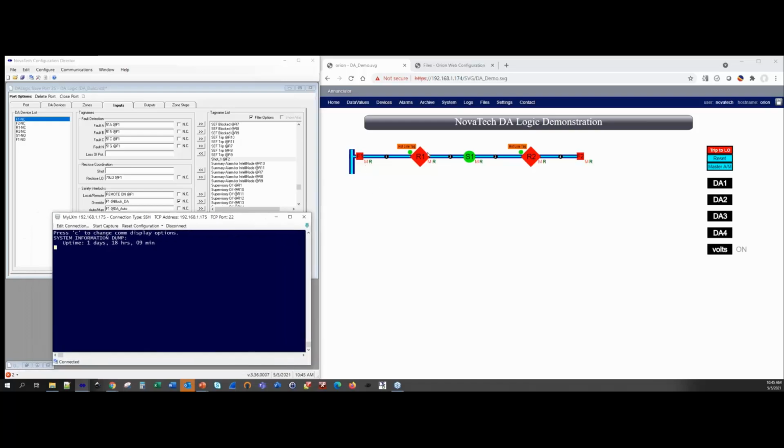So I've got the system normally set. I'm going to turn it into auto to enable the system, and all of those M's got changed to an A. The R, I can put a device into local, or I can put it into remote, so supervisory is off. If I put it in remote, supervisory is on.